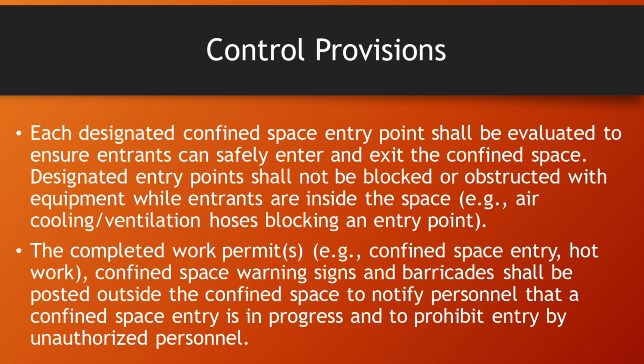The completed work permits, for example, confined space entry and hot work, confined space warning signs, and barricades shall be posted outside the confined space to notify personnel that a confined space entry is in progress and to prohibit entry by unauthorized personnel.